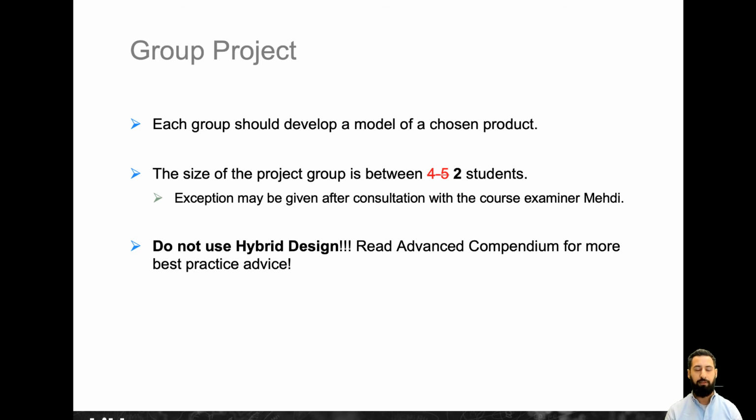One very, very important detail is that you do not use hybrid design. This is an option that you can Google about. Hybrid design in CATIA. Make sure you remove that from the settings. It is highly advised in the compendiums also and in the tutorials. Do not use hybrid design.